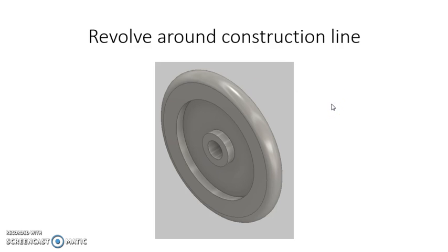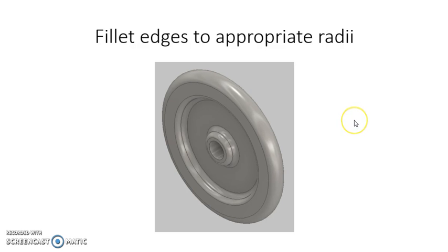After you have completed the revolve feature, then it's time to go through and add your fillets. You're going to see TYP in the dimension sheet. TYP means typical, which means every single corner that looks rounded, that looks about the same size. But the TYP tells you, yes, they are indeed. That is confirming they are the same size. So those are all the same radii.